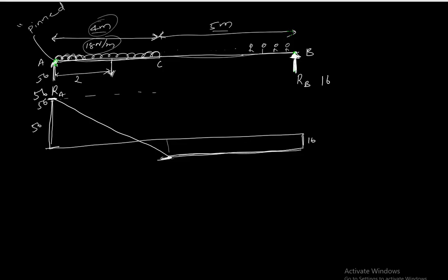Okay, now somewhere here this is crossing the x-axis line. This is intersecting the x-axis line, and we need to find where. The significance of this point is that at this point the forces are 0. The sum of all the forces, the shear force is 0. The beam sees no load at this point. Okay, and we need to find where that point is. All right, let's go about doing that.